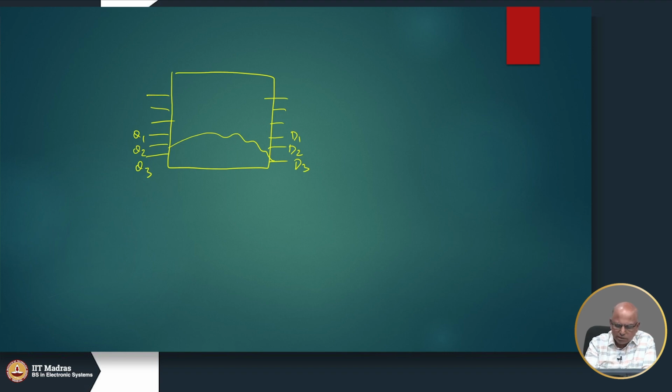And like I mentioned earlier, we have to somehow cause a transition here, a rising transition maybe, and then also a falling transition, both. So just like we had stuck at 0 and stuck at 1, we can identify a path which is too slow to take the rising transition.